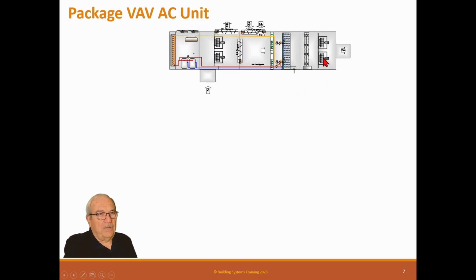So basically we have a supply fan system, we have a return fan system. So the air from the space is induced by the return fans, comes through here, goes into this chamber, and if we're in normal mode, it goes through the return air damper, through the filters, through the cooling coils, through the electric heater coils if it's got any, through the supply fans and back to the space, and this is the circle. We've got a full economizer here.